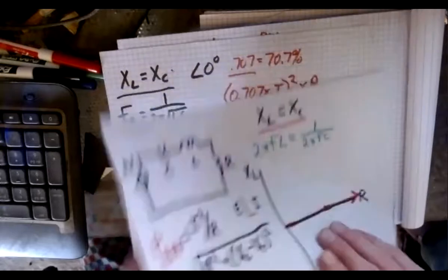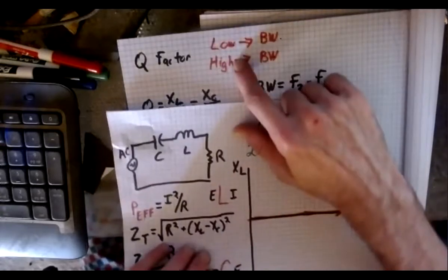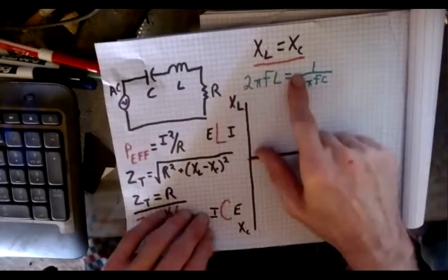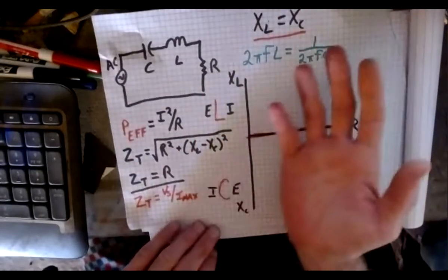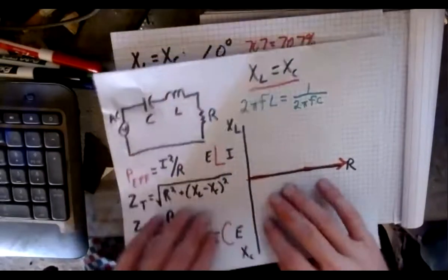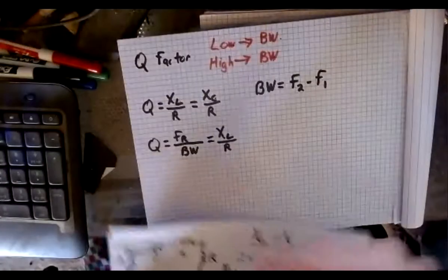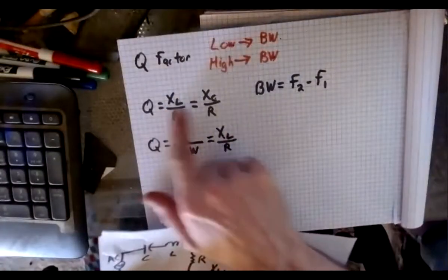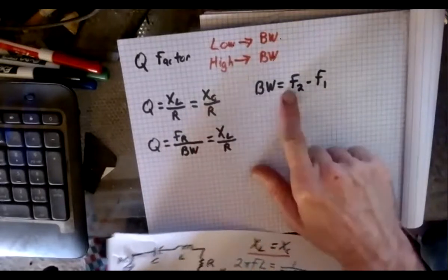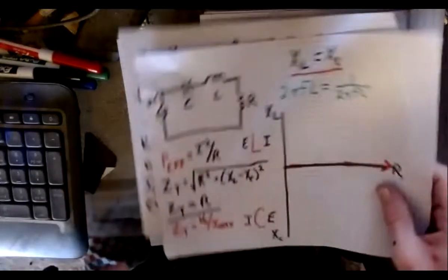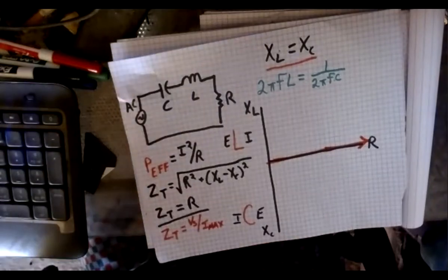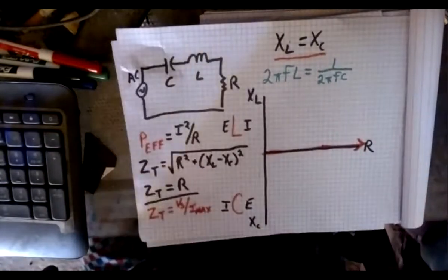So pretty much from the get-go, you just have to decide, do you want a high Q or a low Q? Base your components on that, pick them, set yourself up, plug this through, find out what your purest efficiency model is, and then go through, do your math, and then you basically have your ideal circuit. And yes, we can plug with these formulas like this, like that. All right. And that, my friends, my young gentlemen technicians, is series resonance from my point of view.